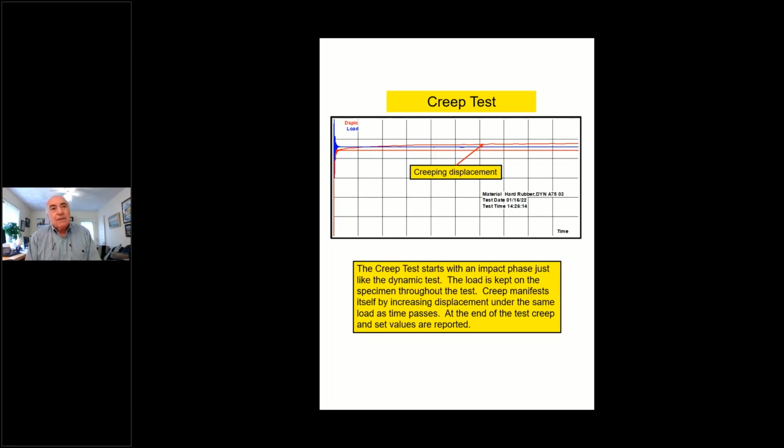Meaning, if there's a danger of leak, the O-ring has to recover within its capability as soon as possible, so the leak will be minimized. And there is the natural frequency characteristics and the dynamic properties come along very importantly.